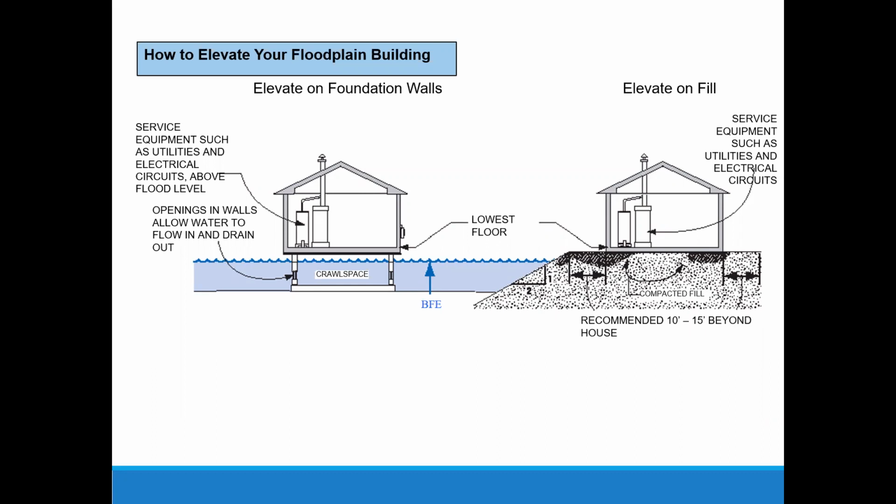The crawl space itself, the interior, is either above or at grade. It's not below grade, because if the floor of the crawl space was below grade, that would make it into a basement. We have had instances where people have put fill around the outside of a crawl space and then made it into a basement, which is non-compliant. That's why we are here to answer questions like that. We could have helped them avoid an issue like that.